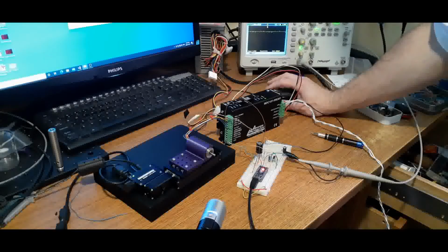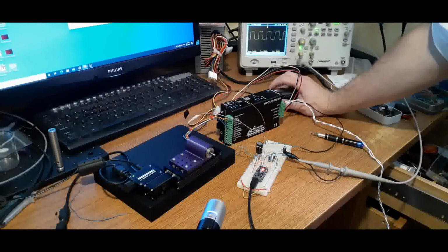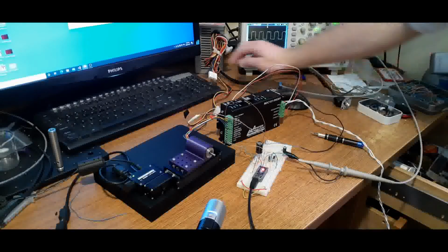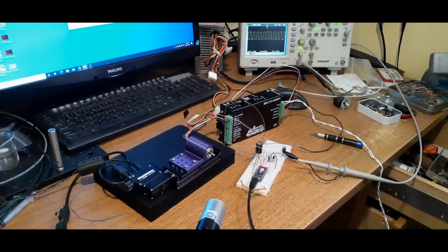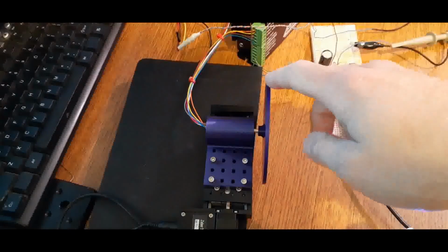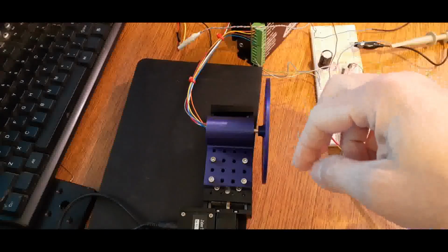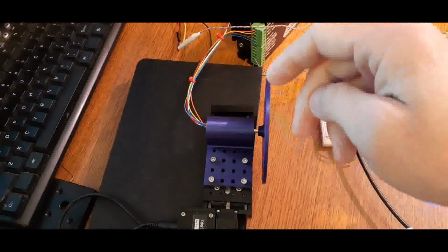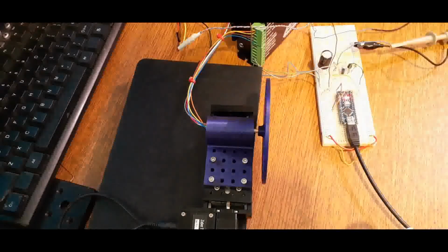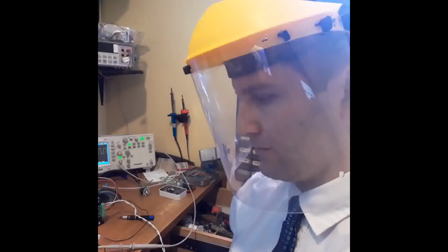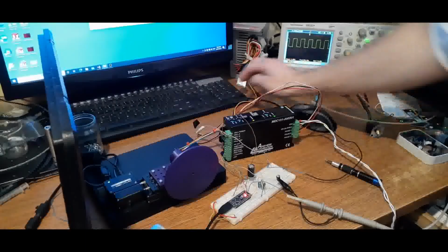The first test without any torque load shows the motor can achieve a top speed of approaching 60,000 RPM. The reality is that when a glass disc is attached, the top speed will be reduced by the amount of air resistance torque. I 3D printed a glass disc analog since I don't have the axle attachments at home for the actual glass disc. As you can see, the heat stresses from 3D printing on the thin plastic piece cause it to warp slightly. This unbalanced load might be dangerous to run up to speed. Let's try anyway.